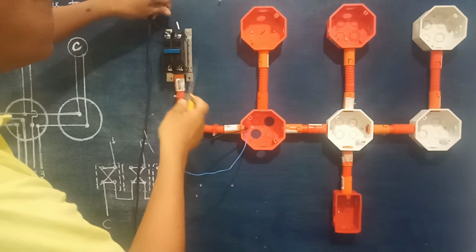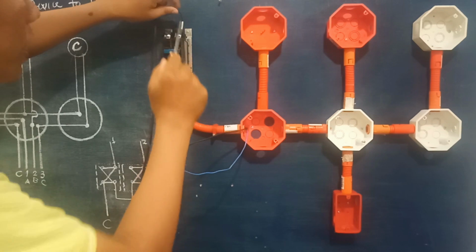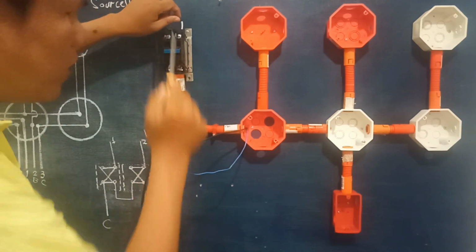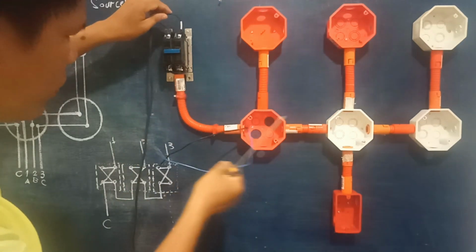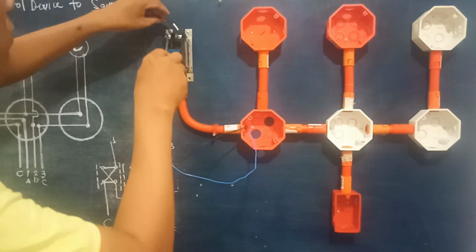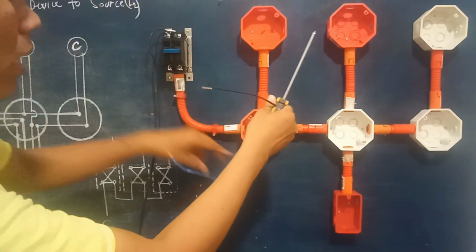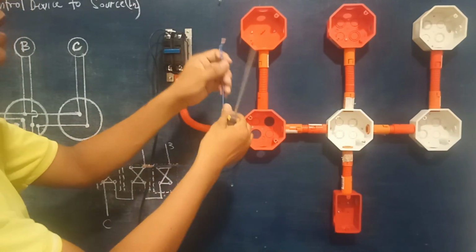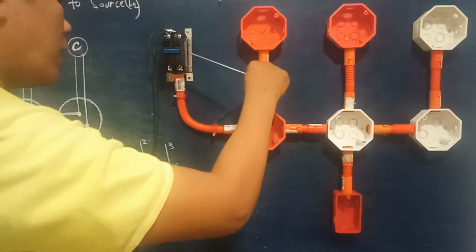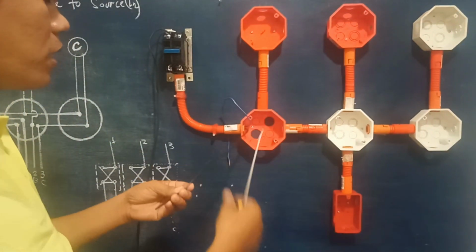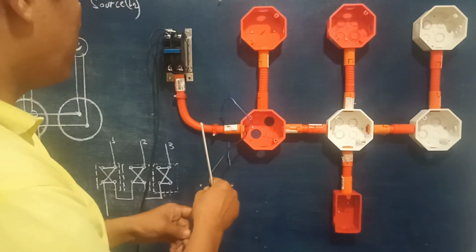So around this part, as you said, this is line 1. This is intended for the neutral line, and the neutral line jumps over here. Okay, so this is in a color of blue wires. The other side, live wire or line 2, is in the form of a black wire. So in our discussion here, we use the blue color wire as our neutral line, this one, and the black color right here is intended for our hot line or the live wire.